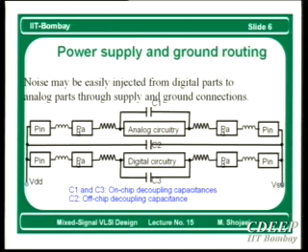I'm not going to two different VDDs, because I could simply disconnect this line and connect the VDD analog here and the VDD digital here. Usually this is not recommended. The main reason is because after all, these analog and digital modules have the same substrate. And if they don't turn on simultaneously, then the circuit will face the problem of latch-up. Therefore, it is not recommended. It is recommended to use the same level as long as levels are compatible. Means I want 2 volt, therefore it's compatible. But if I need 2 volt for digital and 5 volt for analog, then there is no way, right?